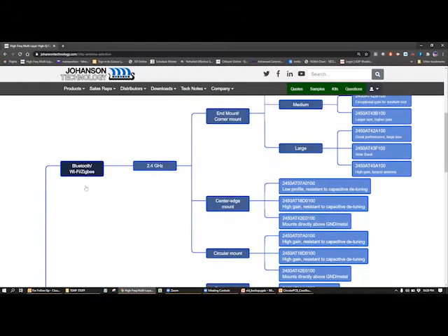And this guide can take you through the steps of ultimately which part number will be best for that shape and size. There's no exact way of going about it, because we do sometimes recommend more than one antenna part number for that frequency, for that size, and for that ultimate position that you have selected.